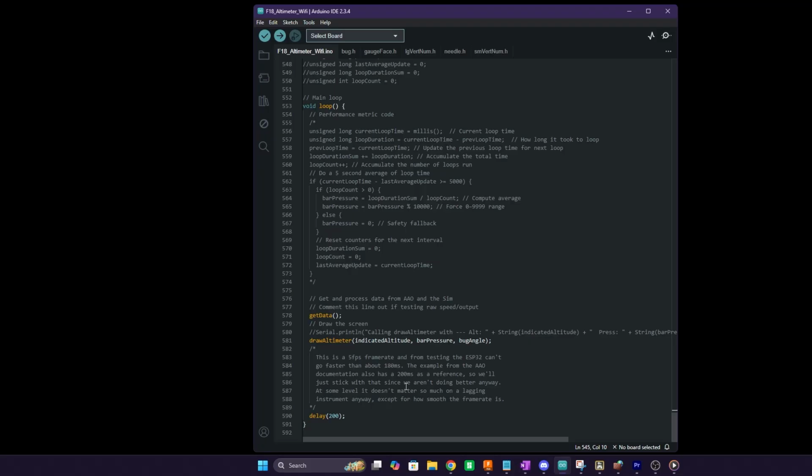It doesn't move smoothly. But again, most of the time in the airplane when you're looking at it, those things are not moving that quickly, so I just haven't found it to be a big issue. You can see here that I've set the delay between each request of that data to be 200 milliseconds, so that we're not pounding the PC a lot, especially once you imagine you get 9 of these going, each asking 5 times a second for their data. That could be a lot. So we're just trying to make sure that we manage our workload there.